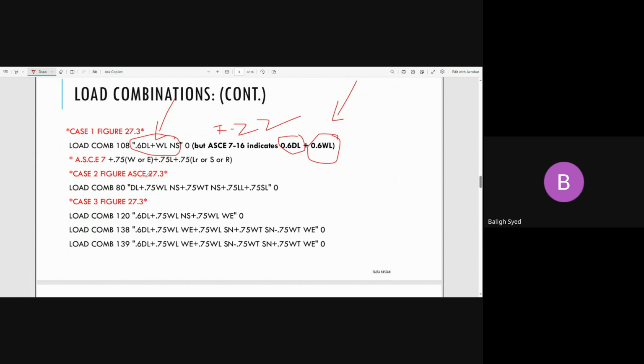If you want to use this load combination, which is the favorite load combination, especially in industrial structures, this defines the minimum gravity load to resist my uplift, and this is the wind load. So it has to be at the service level, like we discussed on the previous slide. Whatever load you calculate, if you are doing the ASD design, you have to multiply all those primary load combinations by 0.7.